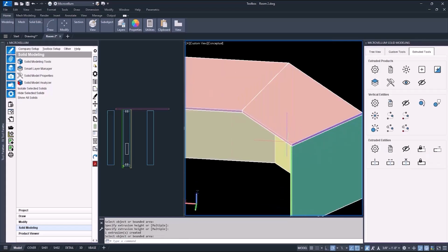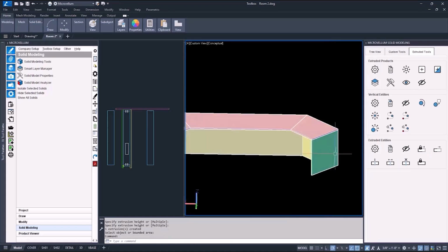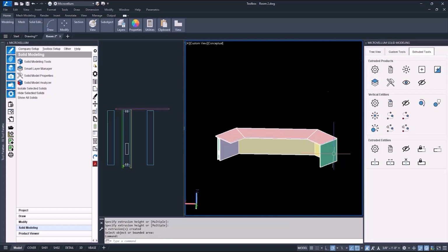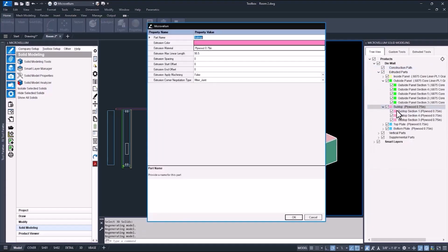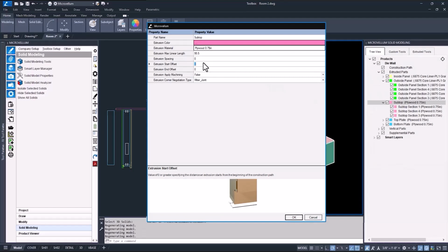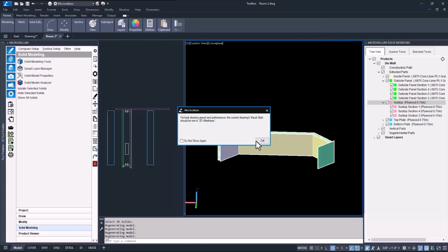Now this will work for the side with no panel, but because I already used that stretch and lock once on the other edge, I'll need to use that again to pull it flush with the end panel. So into the subtop layer, this will be the parent properties, and I'll give just the starting offset a value of -1. A positive value will move the part in from the start of the construction path, where a negative value will start it before.